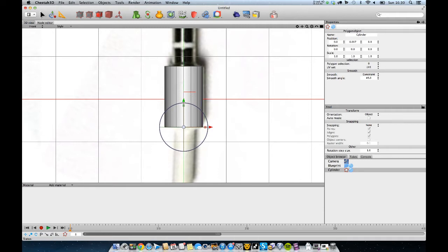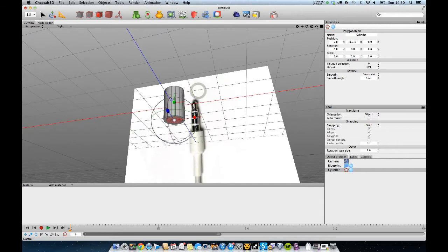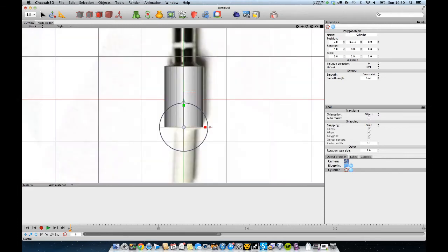So the next thing to do is I'm going to press C for cover. I'm going to select the scale tool. I'm going to scale in. I'm going to just jump into perspective mode here. Have a look at that. Okay, that looks okay. Go back into keyboard 3, and I'm going to cover it again and pull down.